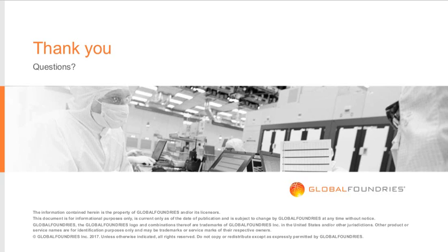For a single device point of view, there are two kinds of breakdown mechanism. One is the gate breakdown, another is the drain to source breakdown. So it depends on the application, either for the switch application or the PA application. For the switch application, the drain to source breakdown is more than 2 volts. So we can do the calculation based on different requirements and